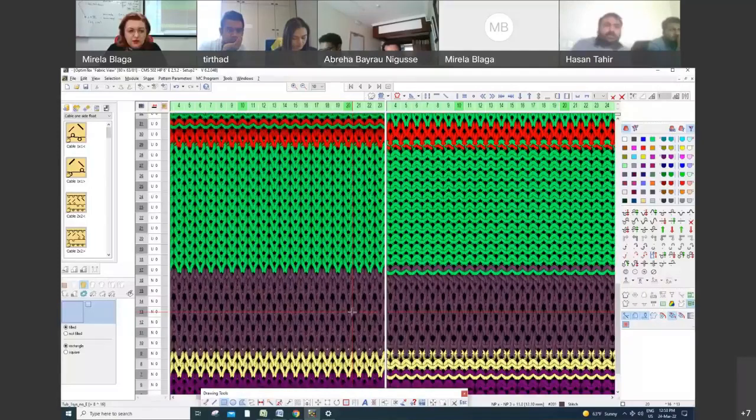You can also adjust or control the properties of the fabric a little bit by playing with the stitch densities. A tighter fabric is a more stable one, versus a looser one where you have more yarn which can be moved between the loops.